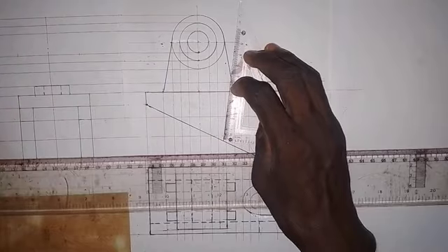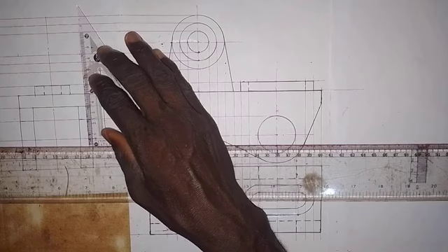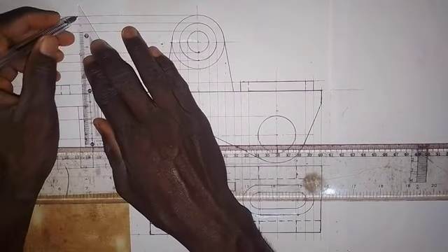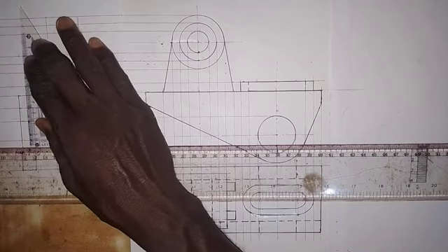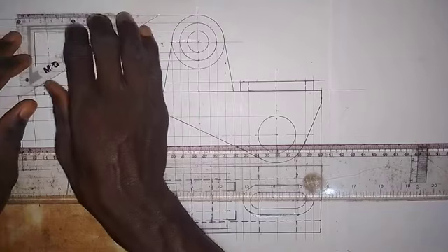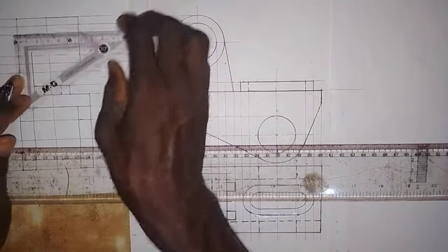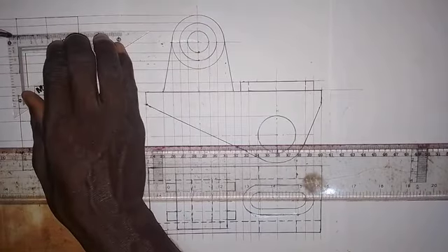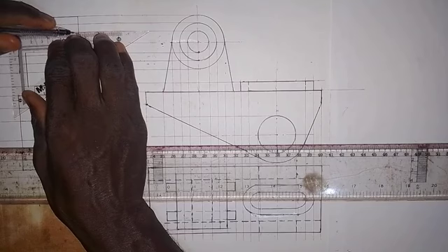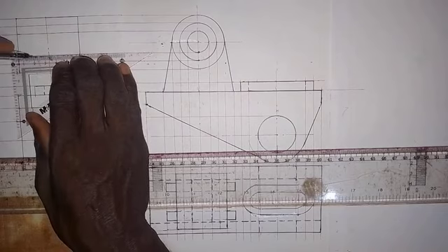At this point I'm going to draw a vertical line. It's going to be a thick line all through. So we make it a thick line, so we draw like this. And then coming to this end, we also draw like this. So we have this now. This line will be a thick line up here like this. Then this hole will be hidden from us, so we make this one a short dashes line like this. Make it a short dashes line to this end, and we also have the same thing here. So make it a short dashes line.